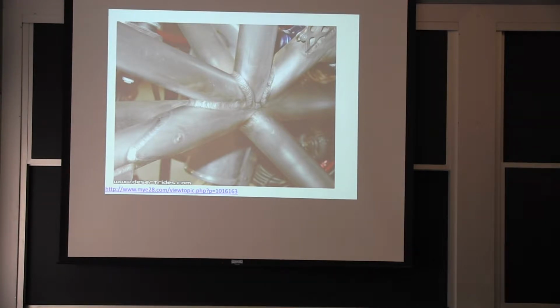Now you could use steel. You would have to paint it, because this was going to be exposed to some atmospheric moisture conditions. One of the reasons for not using steel here is these members were both in tension and compression. So it's a little bit like designing a bicycle.